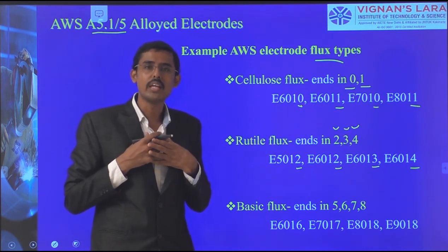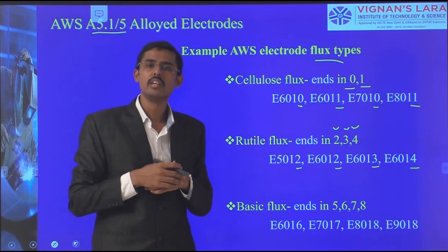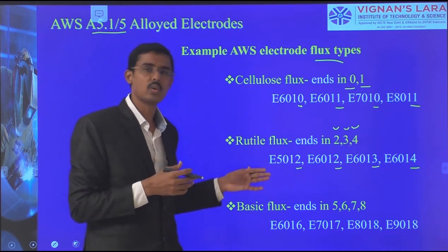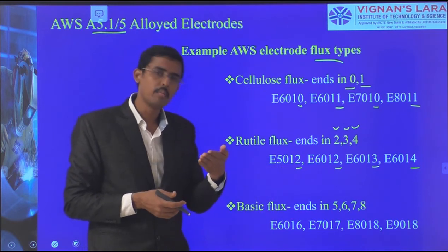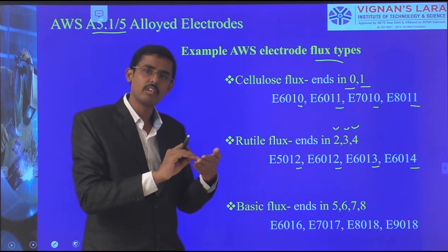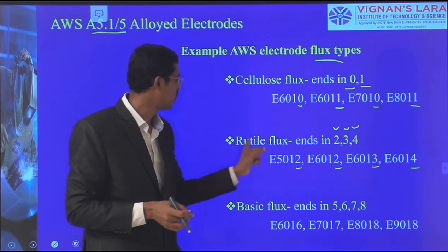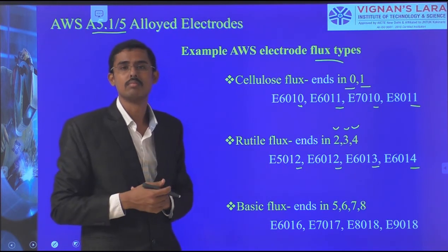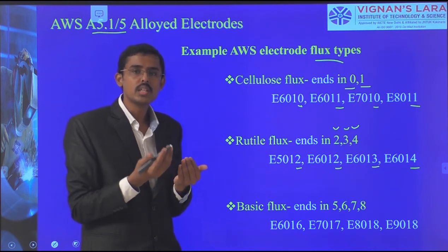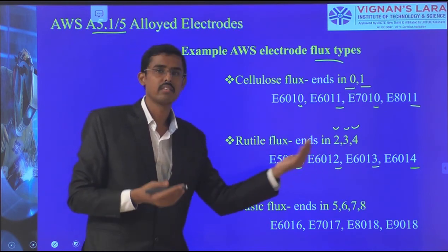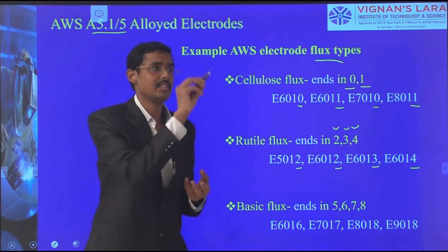Let us consider I am the welding engineer going for an inspection of which electrode they are using. Immediately I can see the electrode; the printing will be there, and I check it. So this belongs to rutile flux. We have to see the specifications, which electrode is to be used there, and whether the welders are only skilled with respect to welding.